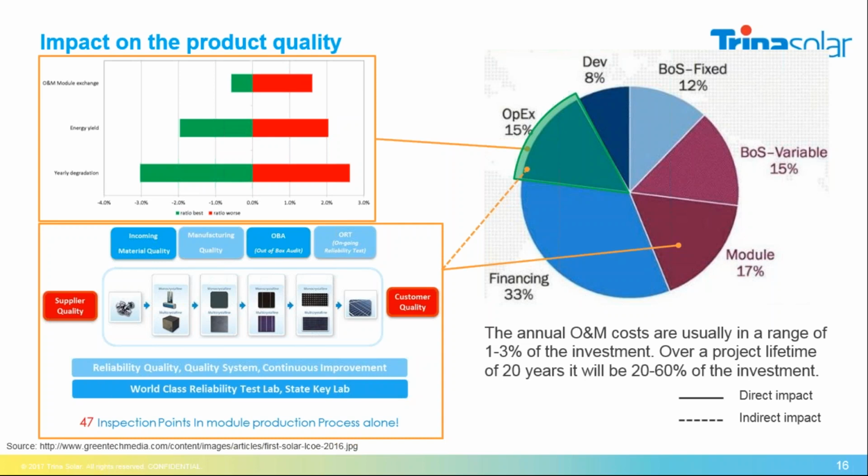Because, for example, if an inverter dies before it is expected to, or a combiner box dies before it is expected to, you have higher operation and maintenance costs, and that means a higher number of replacements. The same applies if the system is not well designed, that means the substructure and the module you have chosen are not working properly together, and you have a high risk of module cracks.